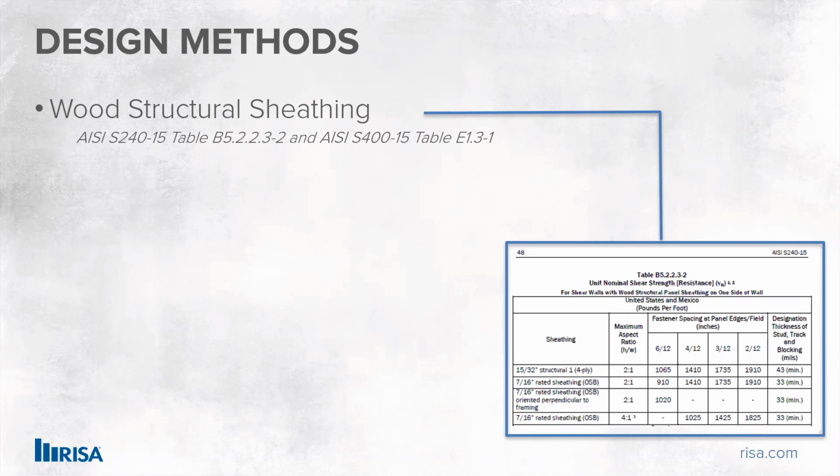Since it is very narrow in what you're allowed to do in your ratios and your sizes, I suggest opening up the code and understanding what you want to pick before you get down the path of even designing your wall. Look at the code, say, okay, I'm roughly going to have about this ratio, and start working from there, so you know what's going to work for you.